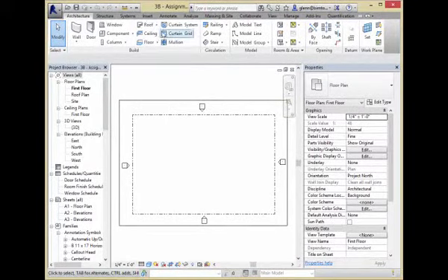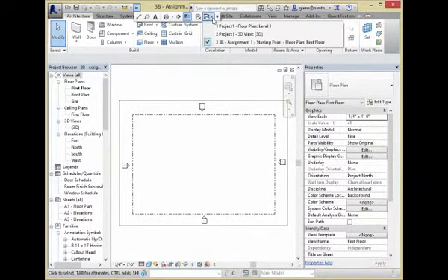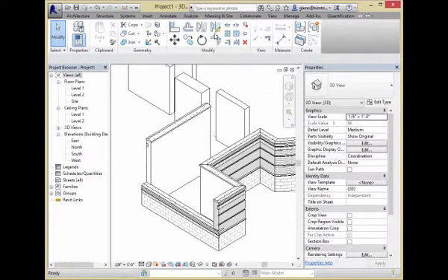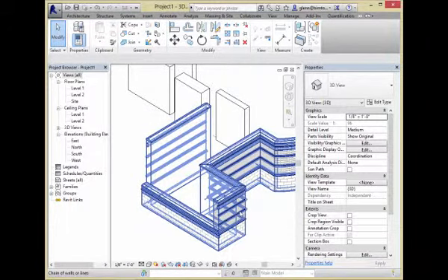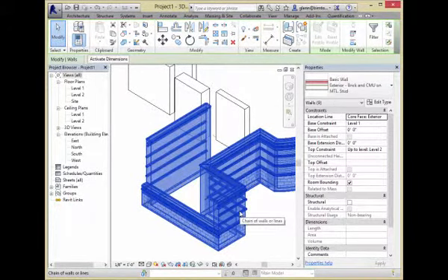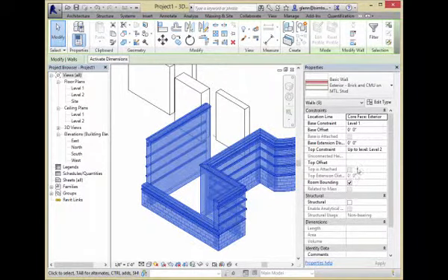Oops. Not that. Let's go over here. I'll switch back over, and I'll go back to project 1. So here are all these walls. I'm going to just tab and grab them all. Okay, now, these are the instance properties. And for all these instances, they have a lot of things in common. Level 1 is in common, level 2 is in common. Column offset isn't in common, so it shows up as blank right now. It's an uneven selection. So if I put a value in there, like 2 or 3, it'll apply to all of them. Okay, so yeah, if you select many instances and then you adjust the properties, it'll apply that change to all the instances.